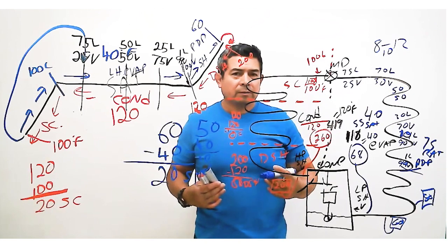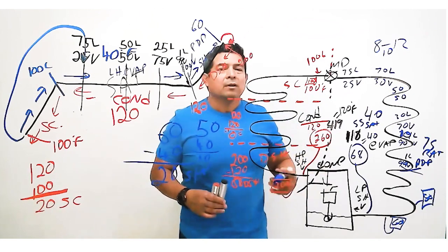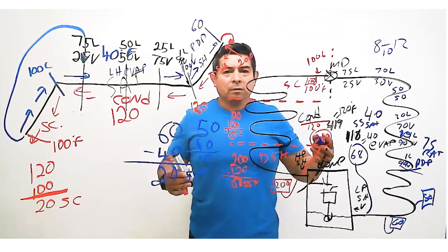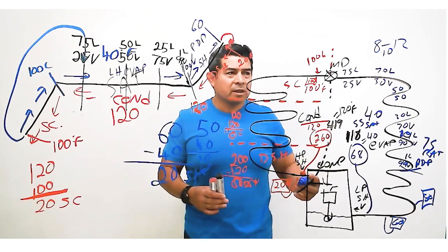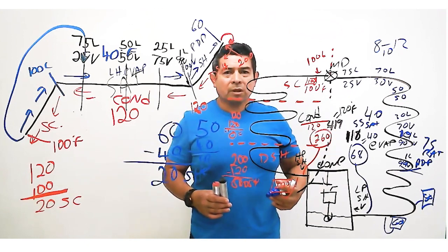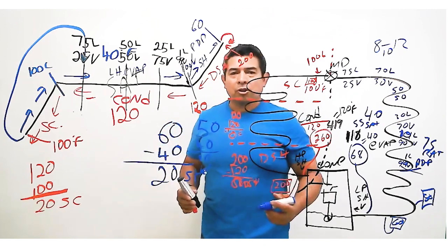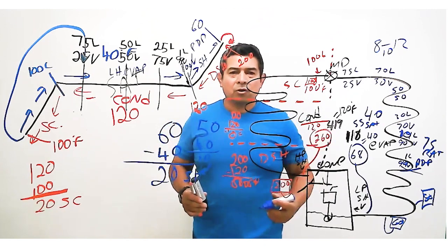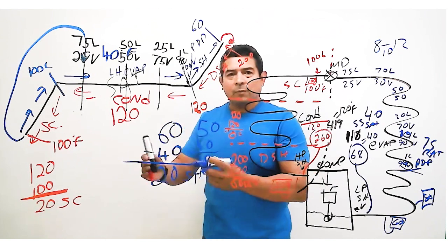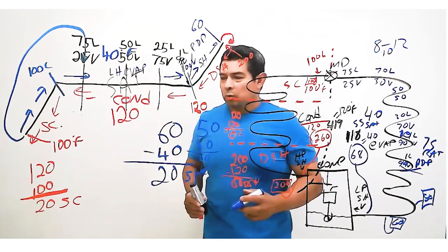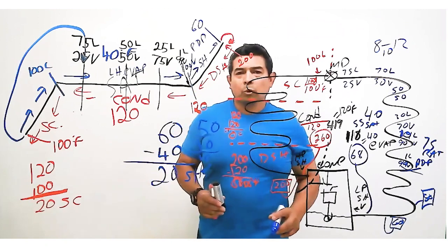But who knows better, me or the manufacturer? The manufacturer knows better. So we look to see what the installation manual says so we can see what our superheat should be. Also, we can look on the panels to see if there are charging charts to see what our superheat should be. The same thing with the subcooling. With the subcooling here, I have 20 degrees of subcooling.